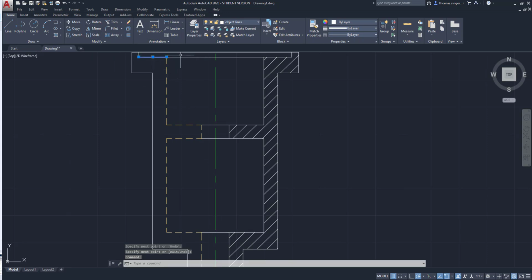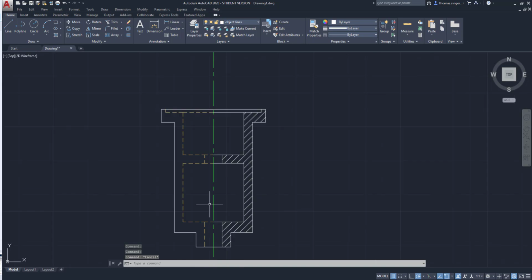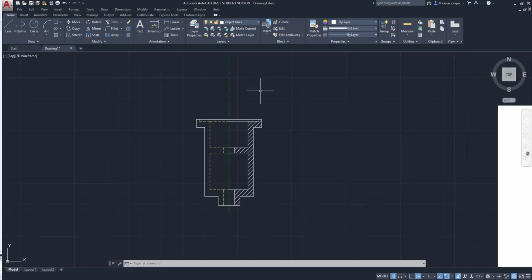And same thing, we'll select the sections to make hidden lines hidden. And this one's going to need to be selected, that needs to be selected, that needs to be selected, that needs to be selected, and drop down, pick hidden, bingo bango. There are the hidden lines. So this side is hidden, the right side is sectioned.